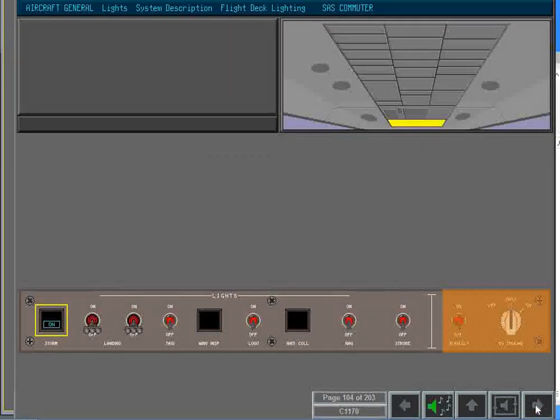A storm light push button is provided to override the individual light controls, including the annunciator brightness selector. Note that the push button is located on the lighting control panel. When the storm light push button is depressed, a blue on light appears and the flight deck floodlights, main instrument floodlights, as well as any annunciator lights come on fully bright.